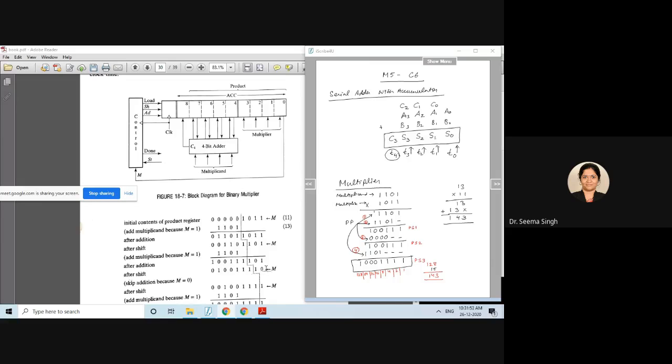Now when you see that 0, this 0 is there, no? After shifting, you get this mode as 0. When mode is 0, you skip addition. You do not do addition, you simply shift. Why do you not do addition? Because actually you were adding 0, 0 only. So the answer is the same. But shifting is important in multiplication. So no addition, but shifting happens.